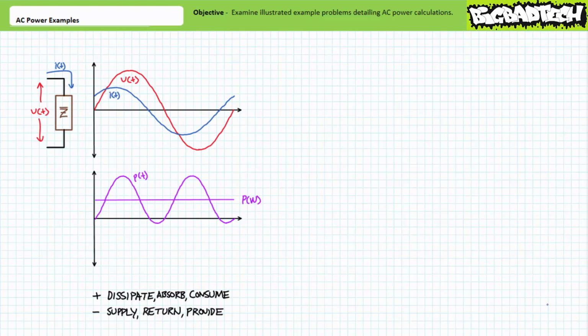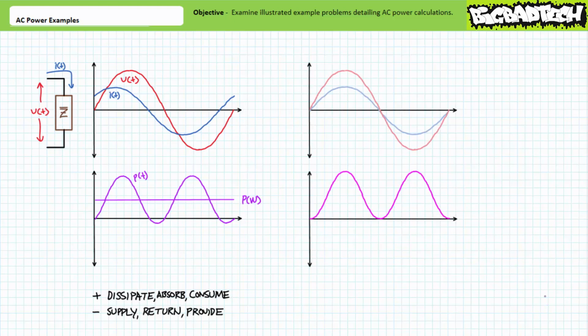some other measurable function. Real power, because it accounts for the amount of phase shift between voltage and current, shifts up or down based on the proportional distribution of positive and negative power over time. If, however, we assume there to be no phase shift between voltage and current, we obtain a similar time-variant power function, only this idealized scenario is entirely above the horizontal axis, meaning power is always positive. If we were to average this imagined state, we would attain a figure known as the apparent power value, symbolized by a capital S, and measured in units of volt amperes, or VA.